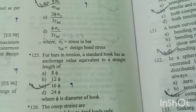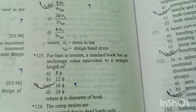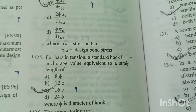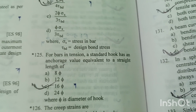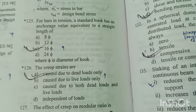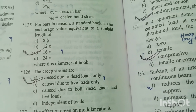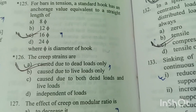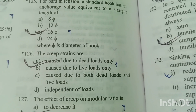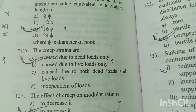Question number 125. For bars in tension, a standard hook has an anchorage value equivalent to a straight length of 16 phi. Option C is right answer, where phi is the diameter of the hook. Question number 126. The creep strains are caused due to dead loads only. Option A is right answer, because creep strains are the long-term deformation under sustained loading.